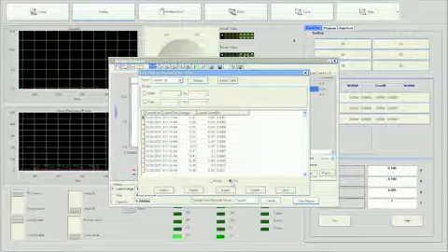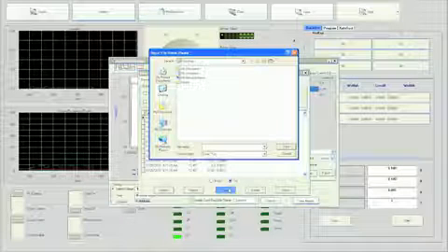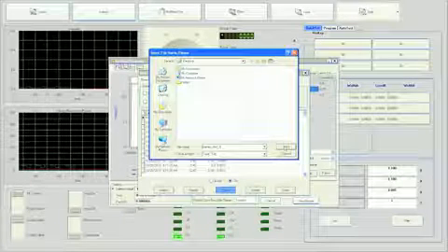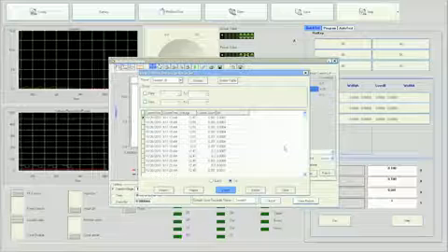We will export to a text file. Click Export. Create a name for your file and click Save. For convenience, we will call it battery_test_1. Then we will save it to the desktop. Now locate the file on your desktop and you will see your data all logged.